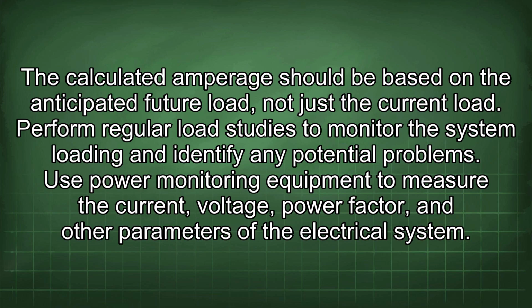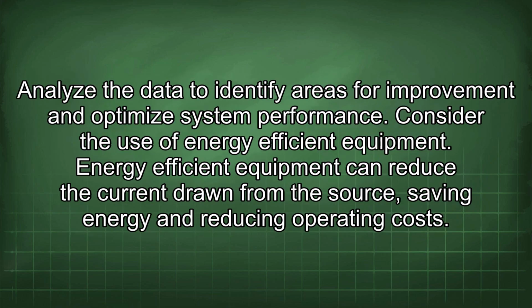Perform regular load studies to monitor the system loading and identify any potential problems. Use power monitoring equipment to measure the current, voltage, power factor, and other parameters of the electrical system. Analyze the data to identify areas for improvement and optimize system performance.